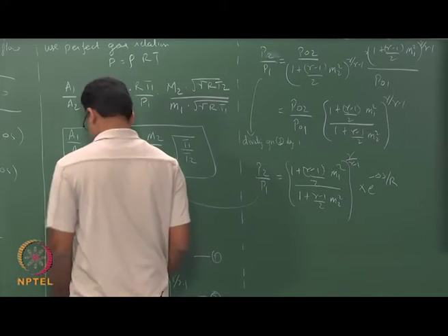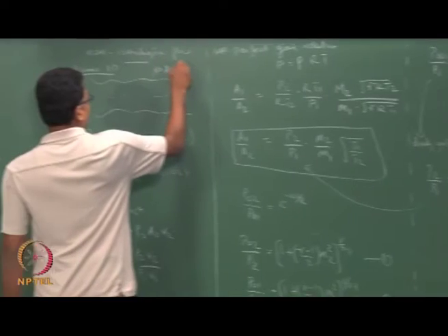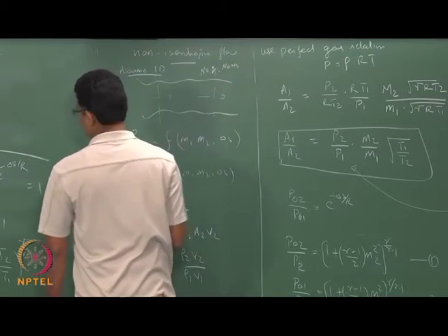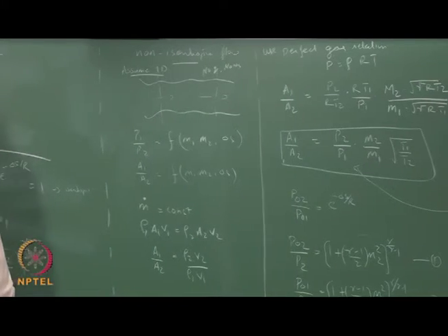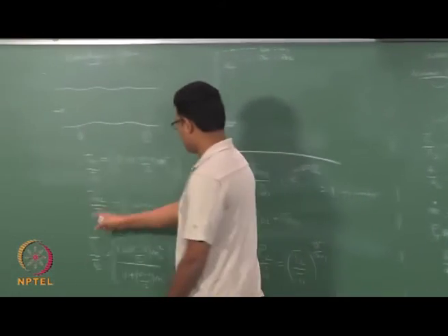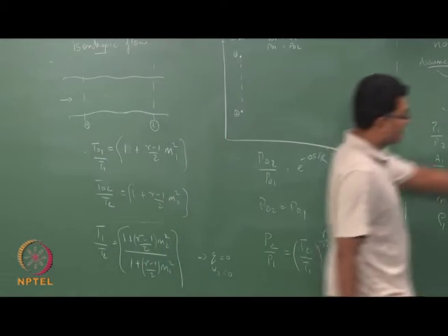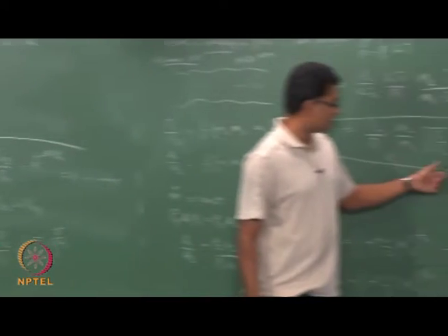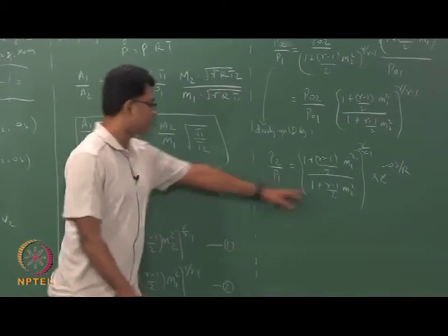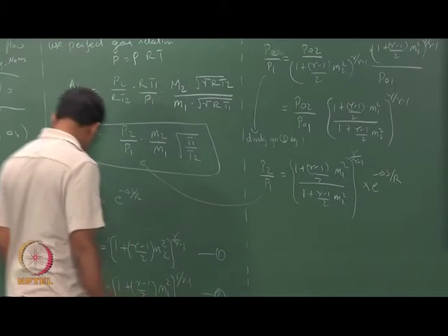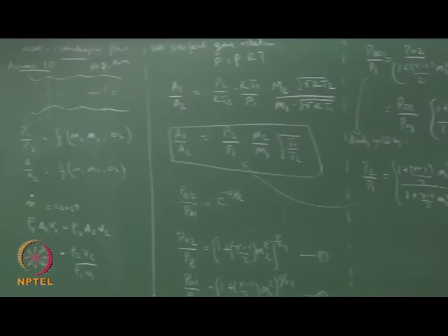Okay. So, there is no Q, no Ws. So, T1 by T2 is this equation, which you obtained using the isentropic relation, but for P1 by P2 there is an irreversibility and hence you have to use this equation. So, I am rewriting that equation here.